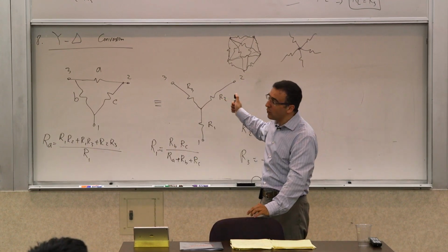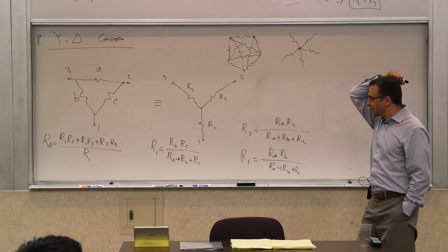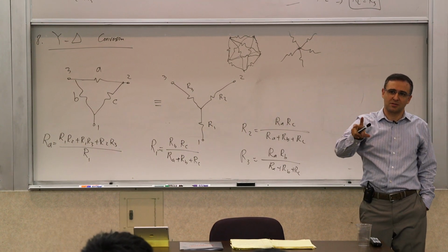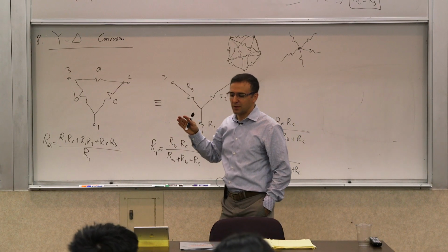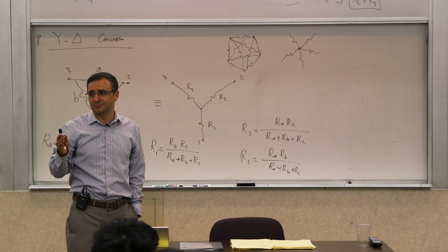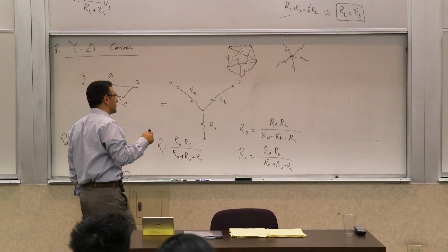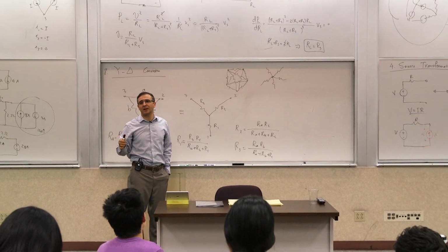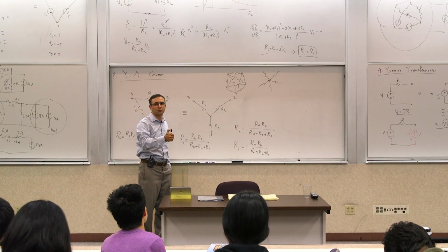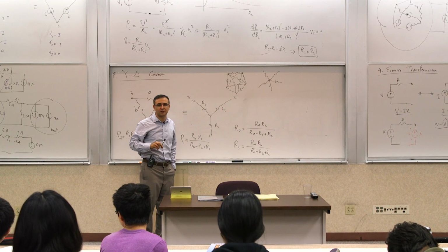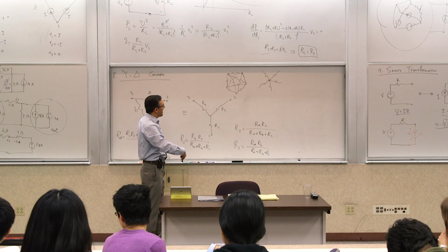This is useful for several different things, particularly 3-phase systems. Now, you may or may not deal with 3-phase systems. If you're dealing with power systems or power conversion, you will. The idea here is that you have 3 different sinusoids with 3 different phases. One is 0, one is 120, one is 240 degrees. So there are three vectors that are 120 degrees apart, and they're rotating, and this will allow you to solve problems.